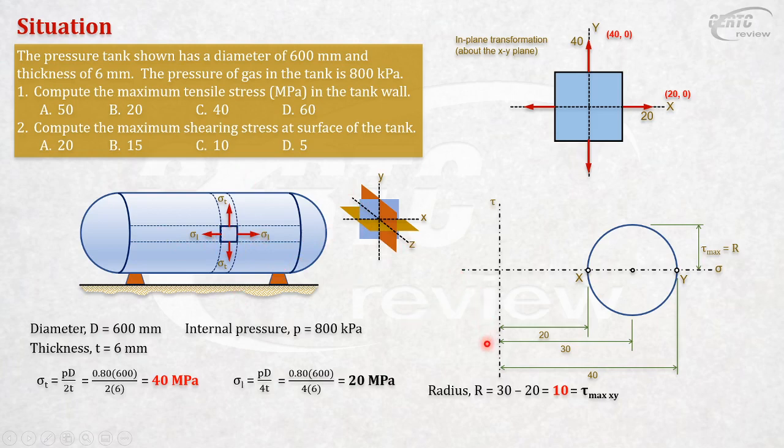So the location of our Z is here. In other words, the plot of the Mohr circle for the XZ plane is this. This is the Mohr circle of the XZ plane. If you got confused, that's fine. Never mind. This has not yet come out on the board. But go ahead and google it to reinforce what you learned. The Mohr circle for the YZ plane is this big one. That's the Mohr circle for the YZ plane.